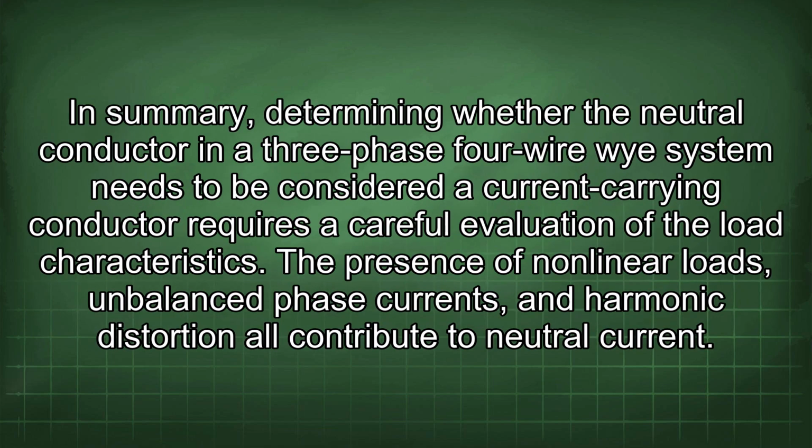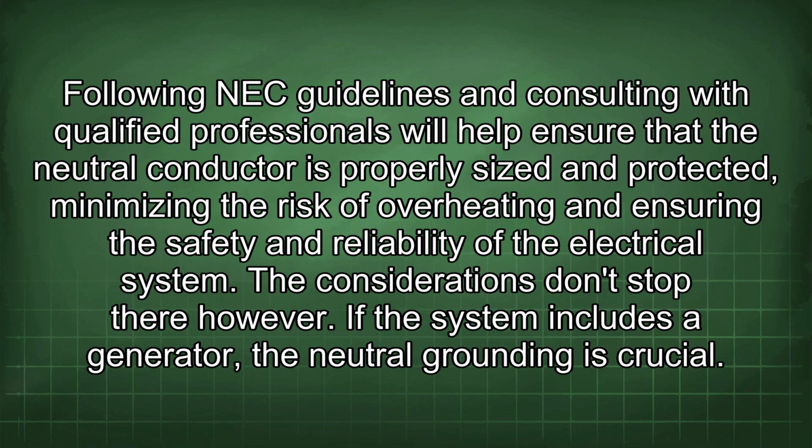In summary, determining whether the neutral conductor in a three-phase 4-wire Y system needs to be considered a current-carrying conductor requires a careful evaluation of the load characteristics. The presence of nonlinear loads, unbalanced phase currents, and harmonic distortion all contribute to neutral current. Following NEC guidelines and consulting with qualified professionals will help ensure that the neutral conductor is properly sized and protected, minimizing the risk of overheating and ensuring the safety and reliability of the electrical system.